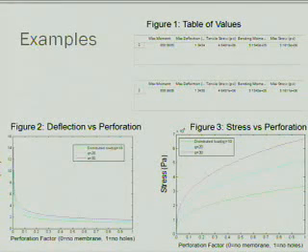And so this is an example of my first order model. Here's our table of values for figure 1. It gives you the moment, the maximum deflection in the center, two stresses, tensile stress and bending moment stress, and then max stress, which is the addition of the two previous stresses. The top box is for no perforation factor, and the bottom box is for our defined perforation factor, and that's just the percentage of area that's left when you take the holes out.